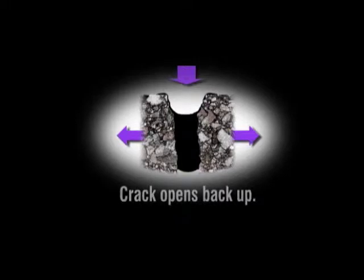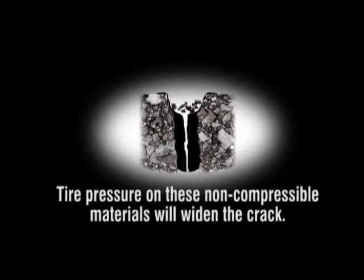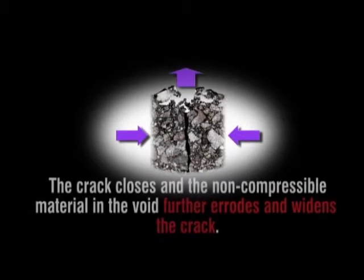This creates a void below the pavement surface because of the sealant loss and allows non-compressible material to enter the void. Tire pressure on these non-compressible materials will widen the crack, and once again, when the temperature warms in the second season, the crack closes and the non-compressible material in the void further erodes and widens the crack. Therefore, as you can see, crack filling for a moving crack will usually fail after 2 years.